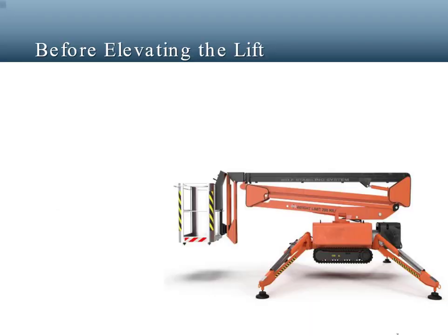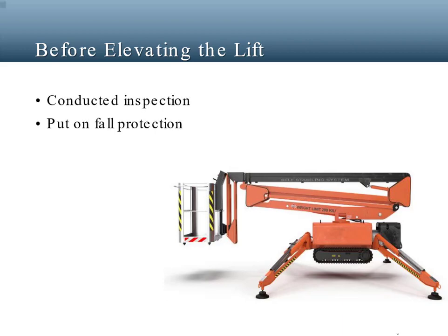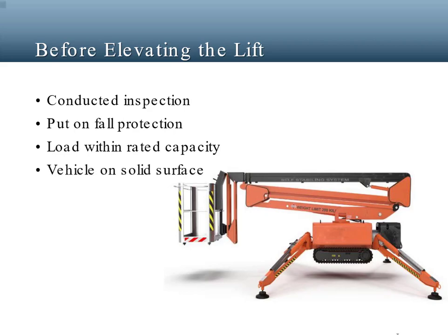Now, here's a quick review of safety practices we've already discussed. Before using an aerial lift, make sure you have performed required inspection. Put on a personal fall arrest or travel restraint system and attach the lanyard correctly. Take care not to overload the lift. Stage the vehicle on a solid surface. And designate a spotter to watch and warn you of hazards in situations where your view is obstructed or there are other distractions like excess noise.